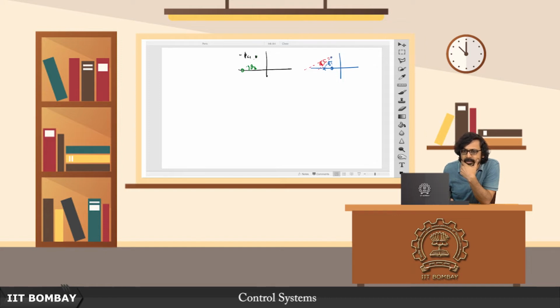Remember, why is this interior angle theta z? Because this is theta z1, this is theta p1. So obviously this angle is equal to this plus this. Exterior angle is equal to the sum of interior opposite angles. So this theta z1 is equal to theta z plus theta p1. Provided you take this as your center and draw these sectors of angle theta z, you will see that as long as you do not cross this green line, it is fine.